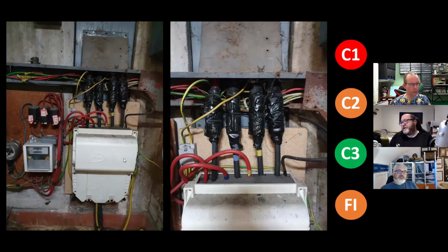What do we think the supply head is? Because if you look at the wiring regulations, we should be able to easily ascertain the DNO connections. If you asked me to code right now, I'd be FI, because I want to look further to find out the earthing system. I can't. I'm with you totally on this, Dave. This is an FI.